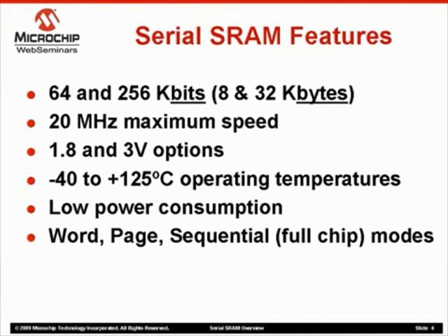The parts can operate in 3 modes as specified in the status register. Word mode, where data is read to or written from a specific word address. Page mode, where data is transferred to or from a 32-byte page. And sequential mode, in which the entire chip can be accessed with a single command.